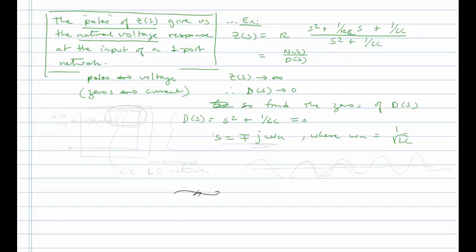Okay, now look at the network. Here's the network that we have, and this will make perfect sense. We have this network, and I'm drawing a box around it, and I'm connecting nothing to here, so we have zero current. Now look at this. If there's zero current flowing through the input, then this resistance has no bearing, right? It's not in the circuit. No current's flowing there. The only active circuit is this right here.